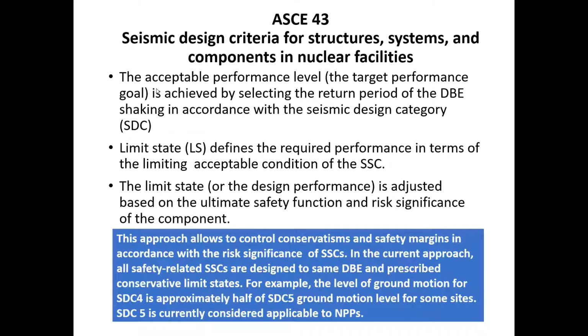what should I design my structure to in terms of performance? Currently, for example, we design a structure to elastic limits or allowable stresses. The question is, do I always have to design to that very strict criteria of remaining elastic, or can I still let my structure yield and go into non-elastic behavior, but that's an adequate design requirement? So that option is provided in the standard.